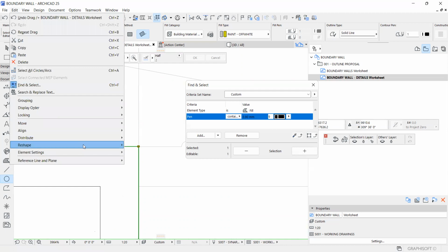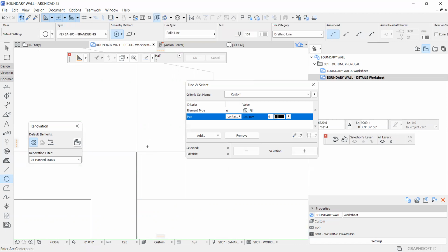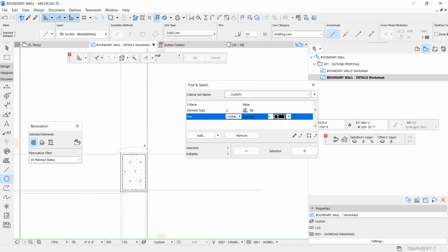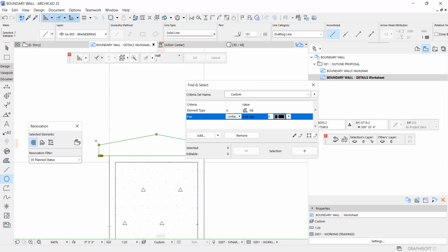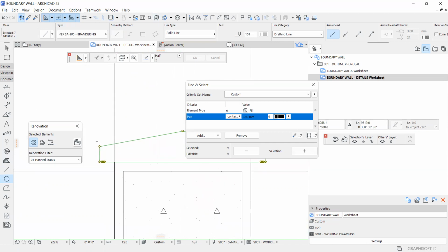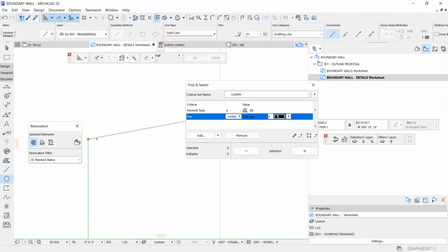It's always important to have that clarity with regards to construction, so that by the time you are modeling, you don't have anything that confuses you. Okay. Now, most of the time, the sills are precast, so they come already finished. All you might do is painting if you want to. So does that mean they usually have a thin film? I'll not call it mortar, okay?